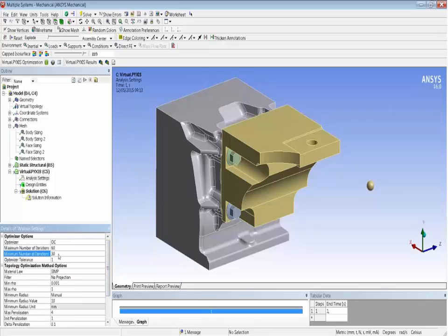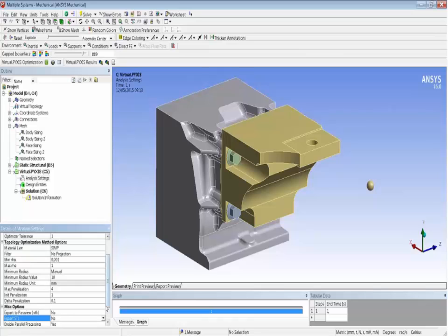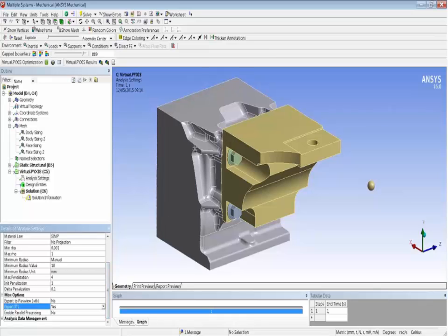In this case, for example, if it's 30, it generates this STL file, which will be used for SpaceClaim, the new feature phases that we are doing today. Also, if you have the possibility to run ANSYS in parallel processing, here you can enable this and, for example, use 4 processors for the ANSYS HPC that you have, to run every ANSYS iteration faster.